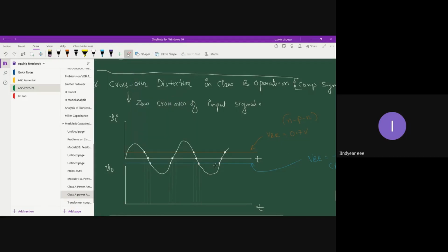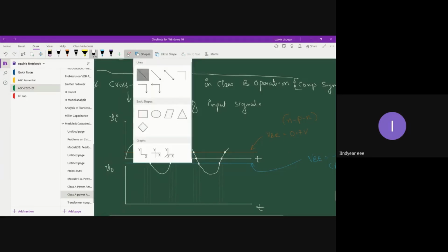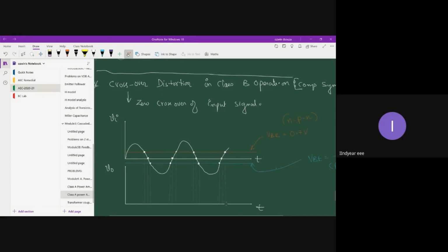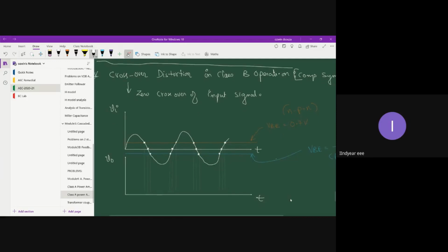So these guidelines will help you in sketching the waveform basically. Okay. That's the reason I'm drawing it in thin lines, because they're not the part of actual waveform. All right. So now that you have drawn the guidelines, you will be able to sketch the waveform. Now the concept of threshold voltage is something like this. Clipper circuits you have studied, right? In case of clipper circuits, the clipping used to take place at VB level or at the desired reference voltage level. The same thing is going to happen over here.